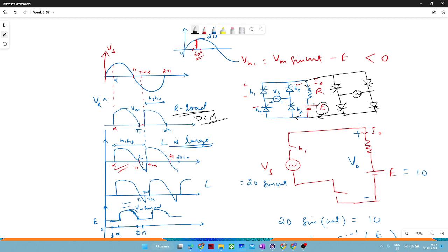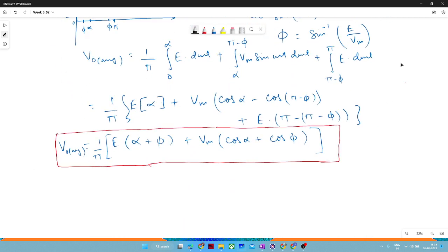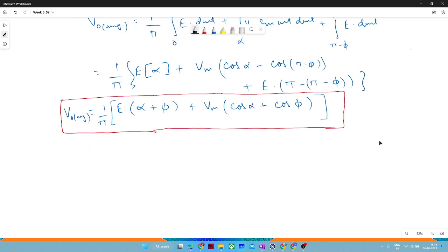But we were talking about when alpha is greater than 90, then basically you are reversing the polarity of voltage, and you are achieving the desirable thing, which is known as regenerative braking. So that was one thing. I hope you might have got partially your answer, and we will see this concept with one problem also.